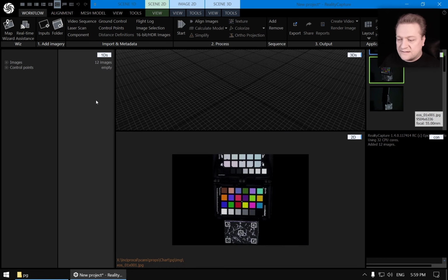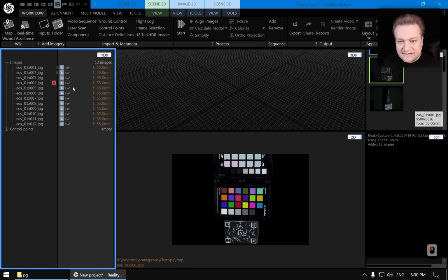One important thing that distinguishes this photometric process from regular photogrammetry is that in regular photogrammetry, when we throw hundreds or thousands of photos at it, if something doesn't align quite well, it's not a big deal, because later when textures are built, there are different techniques to prevent misalignment. However, in the photometric process, we want all our cameras and all our pixels to be as perfectly aligned as possible, because we could reuse that data. And so we pay a lot more attention to alignment and calibration settings than you normally would for the photogrammetry process.